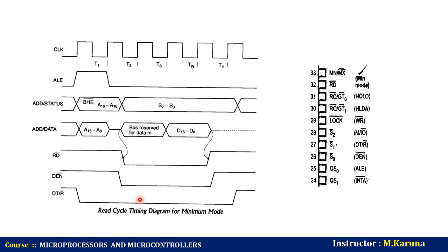There are two types of buses: one is the internal bus and the other is the external bus. If a bus connects two minor components within a major component, it is called an internal bus. When a bus connects two major components, it is called an external bus. The 8086 microprocessor has multiplexed address and data lines to reduce the number of pins required for the microprocessor.